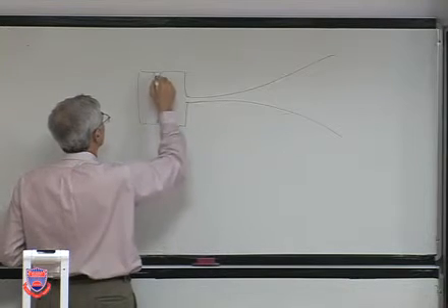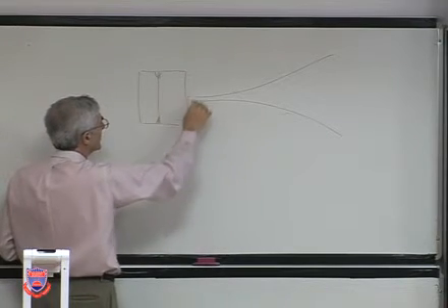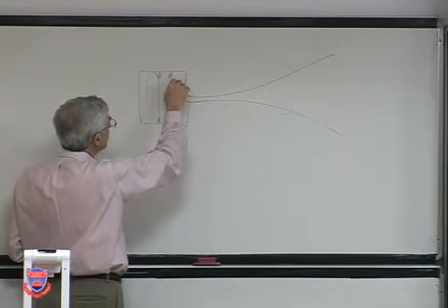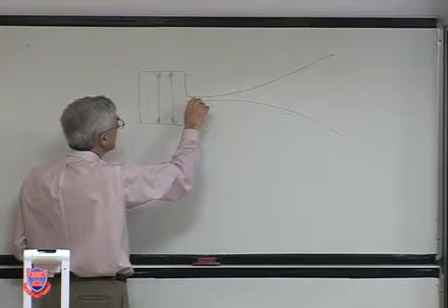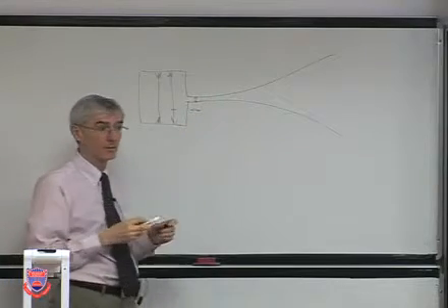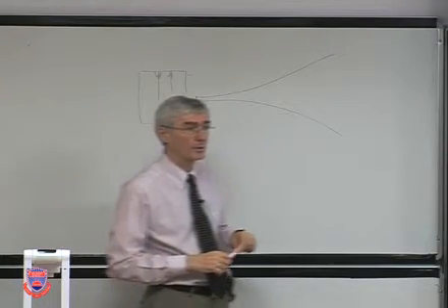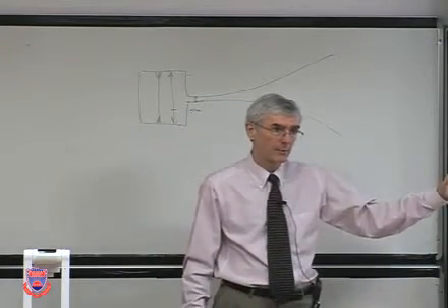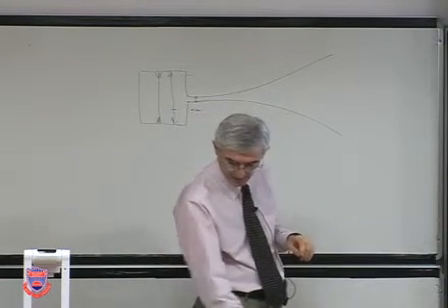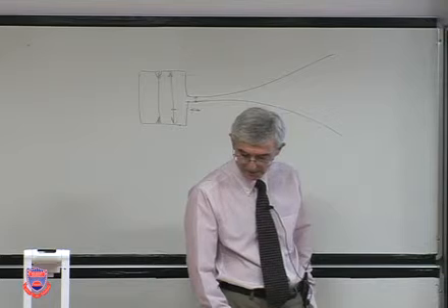There's a membrane that vibrates, and in front of that membrane is a volume like this. So as it goes from this cross-section into this, it amplifies the particle velocity, the tiny one, to a large value. That's one example of how you use an acoustic transformer to get larger flow of particle velocity into the system. So in this case, purely by the ratio of the areas.